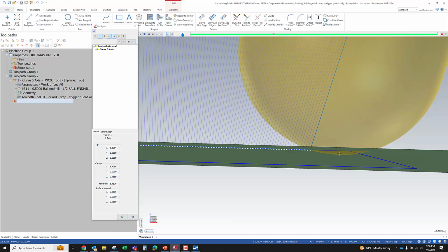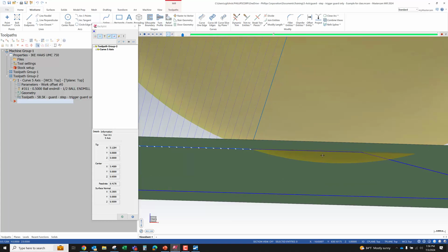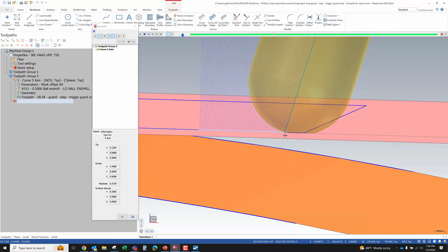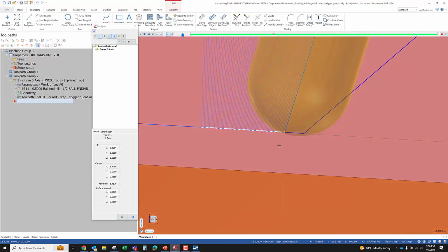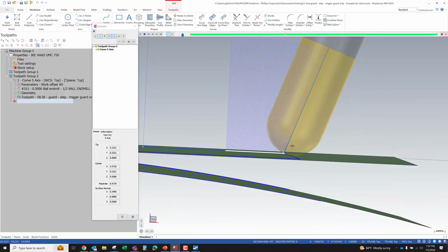Guys, this is the reason why, if you've ever had problems in Mastercam with driving a 3D contour, the 3D contour does not do accurate compensation. And that's why they came up with the toolpath project. So a 3D project style toolpath takes some kind of 2D pattern, whether it's geometry or a toolpath, and projects it down onto a set of surfaces so that we can fix the problem of tool gouging. And so this is what we get when we just say, I just want the tool to compensate to the selected curve.